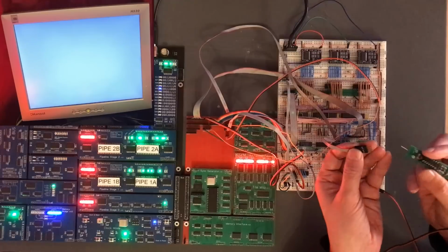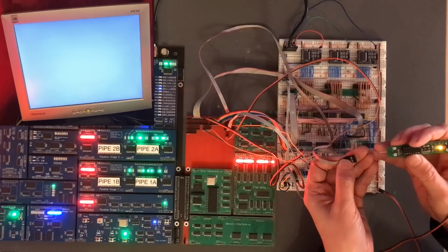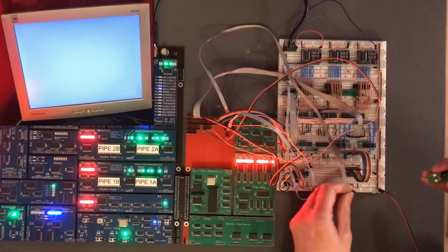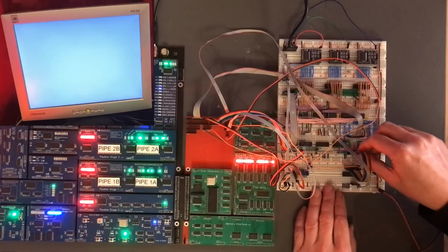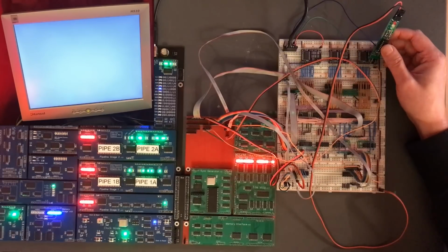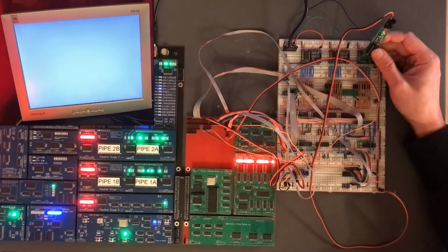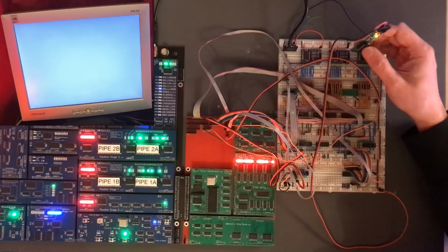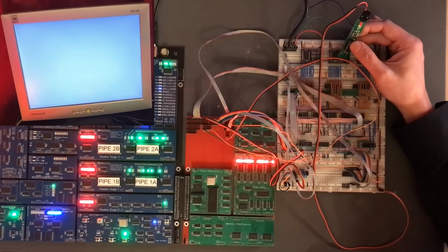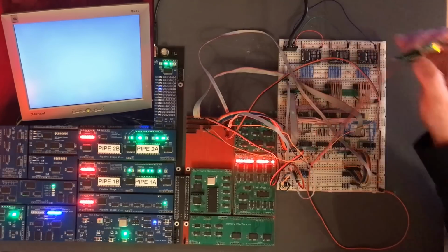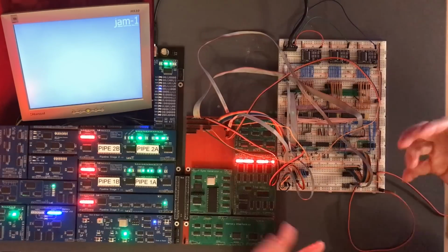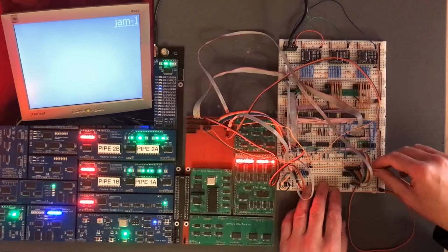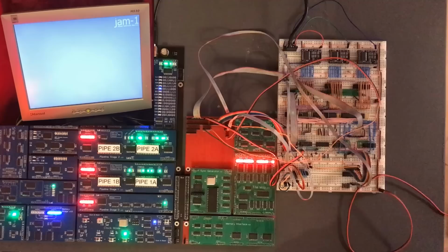So I'm testing the outputs from the tile data now. They are indeed all 0. So that must mean the palette is outputting the wrong data. This should be blue. So we expect this to all be 0. Yeah. 0, 0, 0. Interesting. Feels like the data is getting corrupted on the way to the palette.